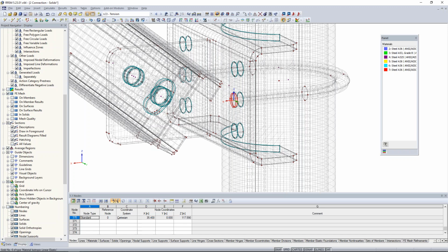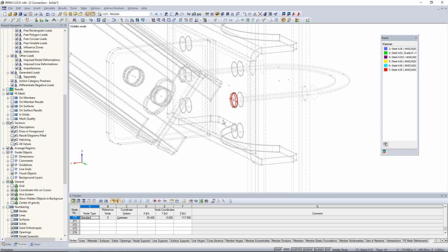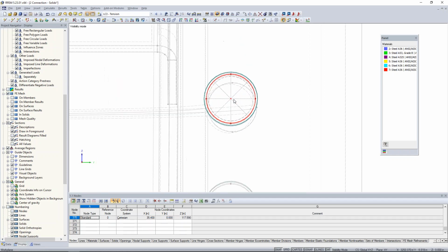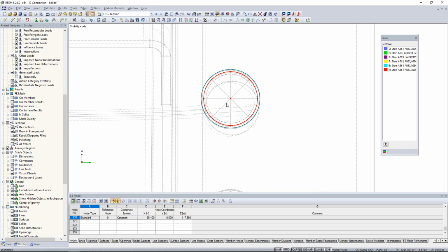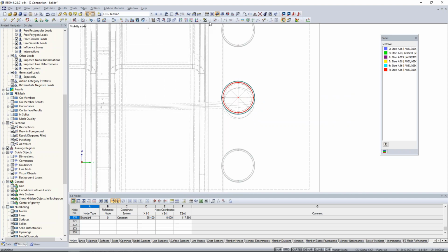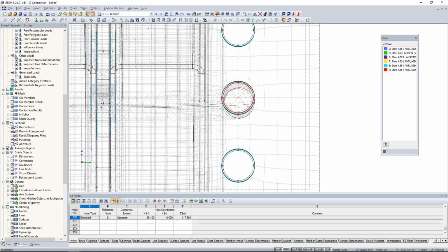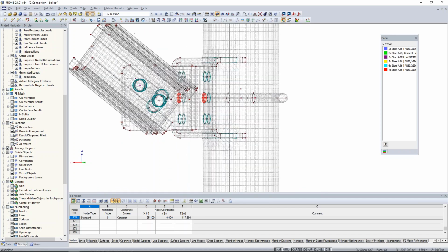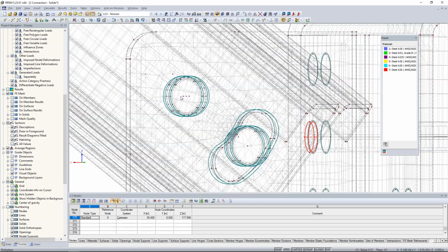And let me take a look at one of these smaller bolt solids, for example, and I'll create a visibility by the selected objects. One thing that I'd like to note when we're kind of zooming in here is that there's actually only 2 FE mesh elements across the entire length. And if we're truly interested in the stresses in our bolt elements even, we probably want to refine this mesh quite a bit. So what I'll do here is cancel my visibility mode, and holding down my control key, what I can do here is select all of these smaller solid elements.